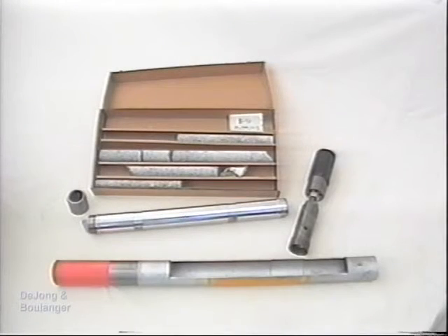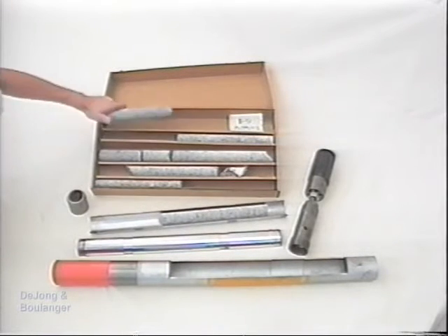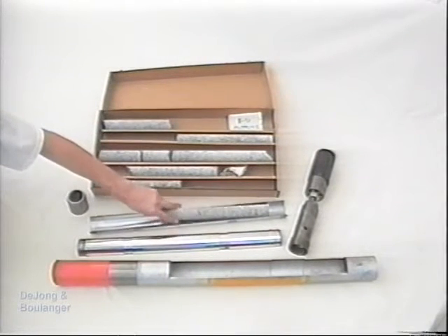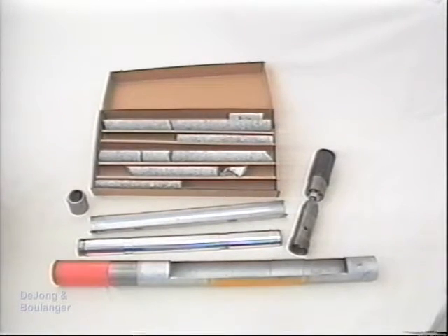By disassembling the core barrel, a continuous sample of the soil or rock is recovered. The sample is measured, identified, and stored in core boxes. After reassembly, the core barrel is lowered to the bottom of the hole and drilling and sampling are continued.